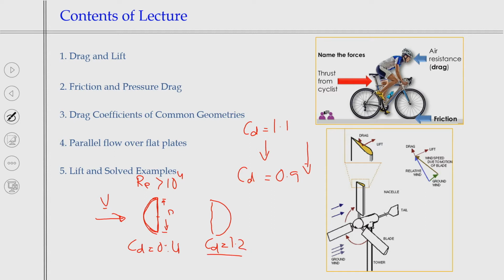That means the drag force exerted when your umbrella is parallel to the velocity will be 0.4 times half rho v square into A, the dynamic pressure times A. But if I hold the same umbrella differently, the force because of this orientation, if I put a dash, will be 3 times the FD force.